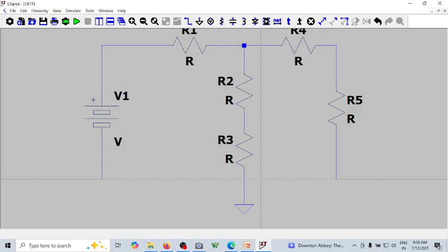What you can do is redo that connection, or you put one extra wire. So I'm just clicking there and then stopping it here. Can you see? There's a dot created. So you can just repeat that. While doing it yourself in your simulator, make sure that you have a dot here. If there is no dot, it means this ground is not connected to this line at all. So it will be connected to only R3. So let me change the values of the resistance.